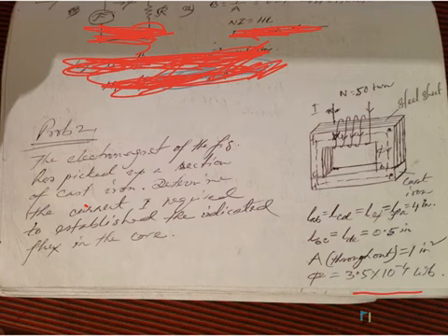And you can see in this example, this core is divided into two parts. The upper part is made of steel sheet, lower part is made of cast iron. And the number of turns of the coil is 50 turns. The current is going through this way. The phi is there. The most important thing you have to look at here is the indication A, B, C, D, E, F. These are the points. The flux path is shown by indicating A to B, B to C to E to F, like that way the flux lines are passing through.